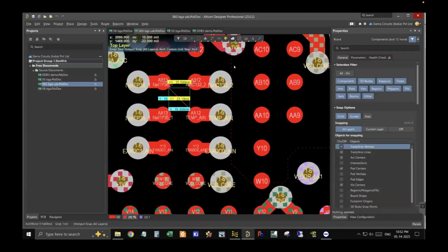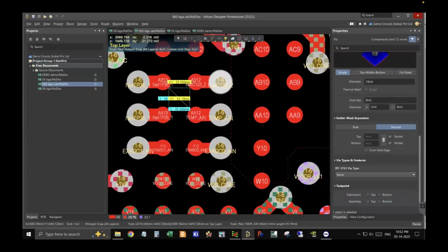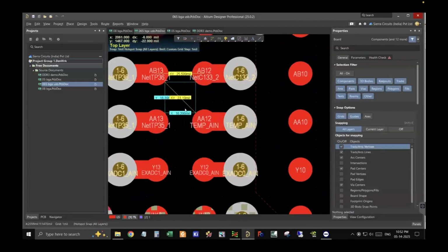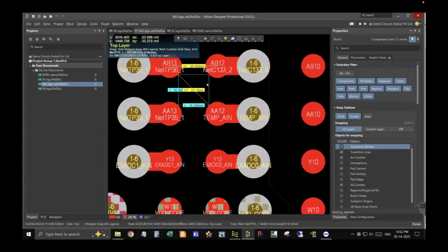Because as you can see, there is open space in this area, so you can easily put the wire over here. But suppose there was no open space, then you might have to put it over here between the two pads. In that case, you have 23 mils, so you can use an 8/16 wire. That will leave you with 4 mils on each side, but you will have to go with quarter ounce copper foil on the external layer. So yeah, that is one thing.